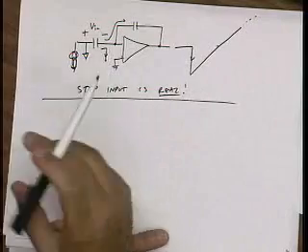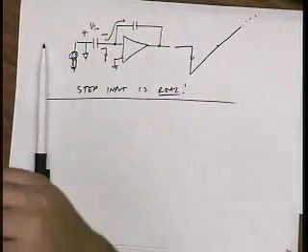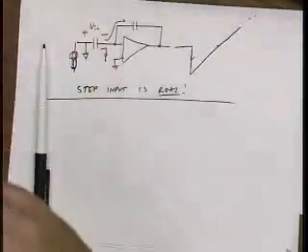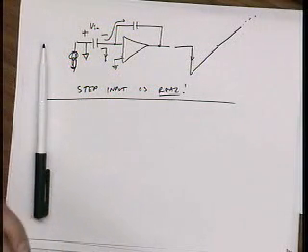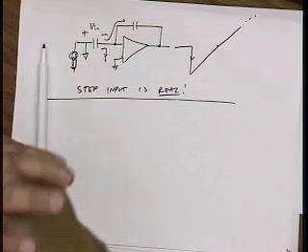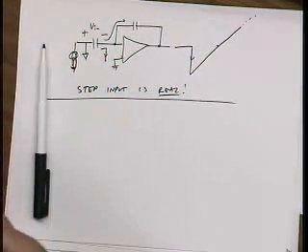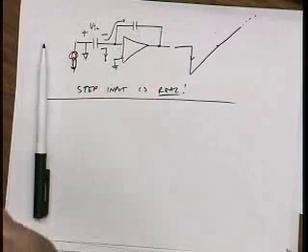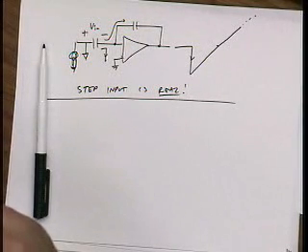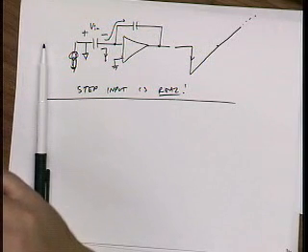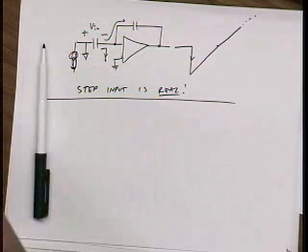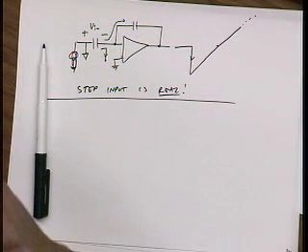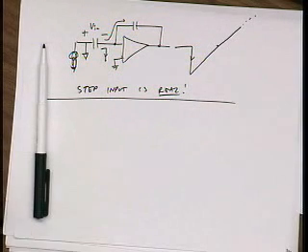In fact, it's kind of interesting that the settling time of a linear circuit is independent of the size of the input, right? I can put in a millivolt, and I have to wait 5 nanoseconds. I could put in a million volts, and still only have to wait 5 nanoseconds. Why is that? Why is it that for a linear circuit, the settling time is independent of the amplitude?